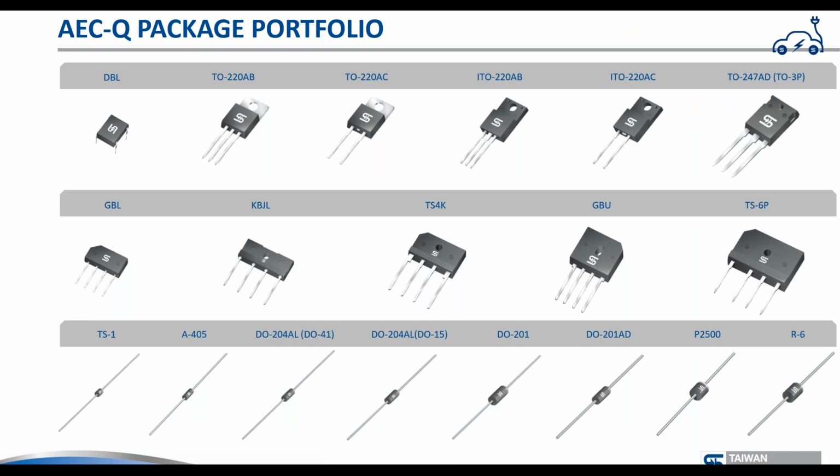Let me talk a little bit, for the people that are not in surface mount, about a quick question here: all these old packages, what are we going to do with them? There's going to be very little rectifier obsolescence here. Obsolescence is caused more by the front end rather than the back end. For example, we have fewer problems than with MOSFETs. There are some MOSFETs out there on 6-inch wafers, and people want to shut those fabs, or the MOSFETs are still on 0.35 micron or 0.25 micron processes. People want to get rid of that, and it's no longer competitive.